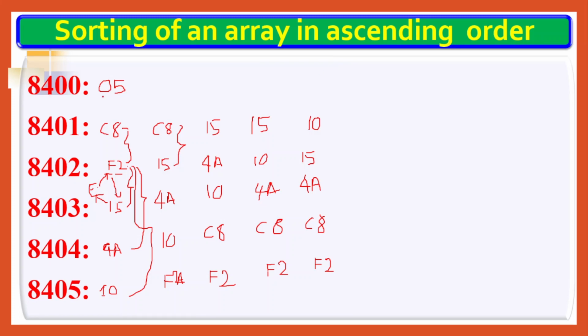So let's start the programming here. The first element is a count, so you will use LDA with the address 8400.